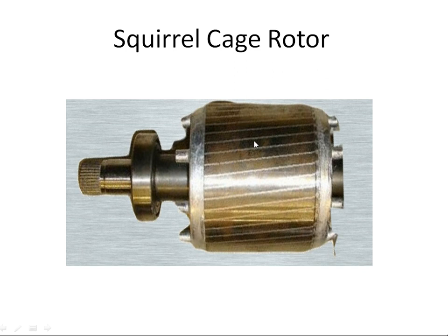This is due to the harmonic synchronizing torque produced, which will make this motor magnetically get locked with the stator magnetic field, running at constant synchronous speed, which we don't want. So in order to reduce that, grooves are provided, and this is known as skewing. The angle of skewing generally ranges from 7 to 15 degrees.